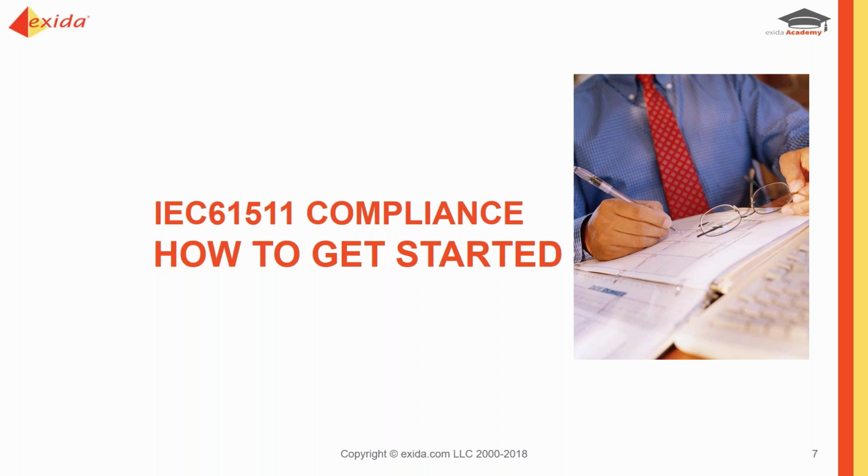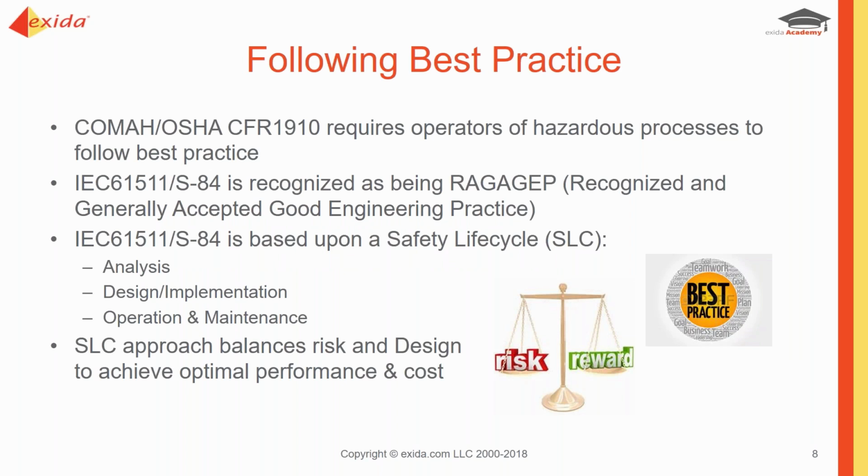Now, the reason that compliance is necessary, of course, is that if you come under either OSHA in the US, PSM for process safety, or COMAH in the UK, then you are required to follow what is known as best practice. So what is best practice? Well, the IEC 61511 or the ISA S84 is recognized as being RAGAGEP or best practice by OSHA and COMAH, and that's recognized and generally accepted good engineering practice.